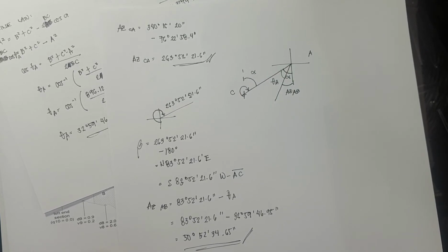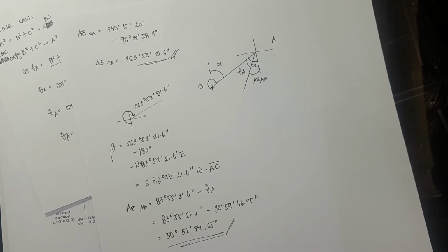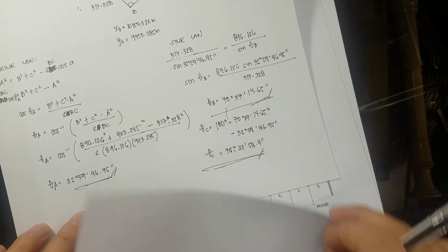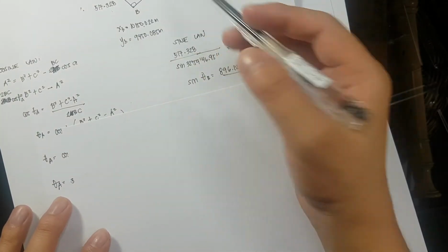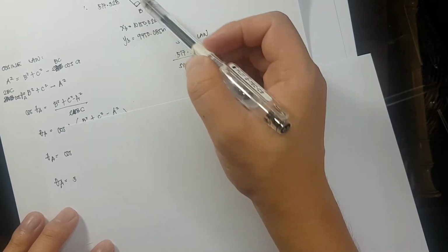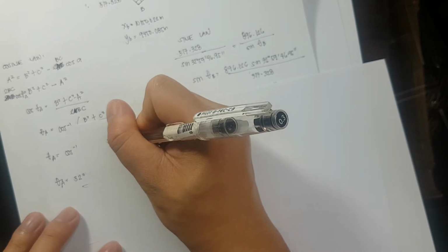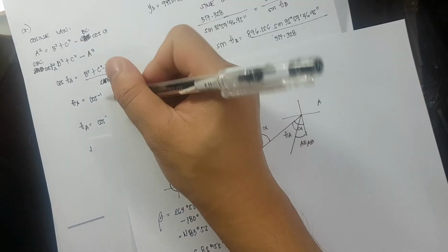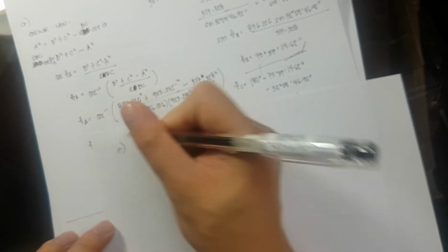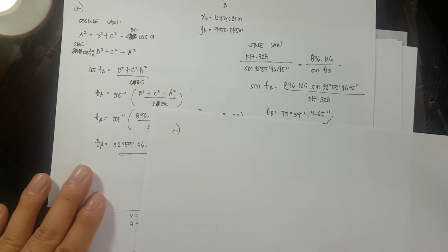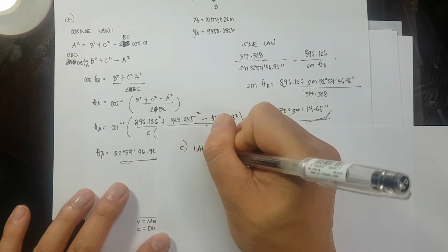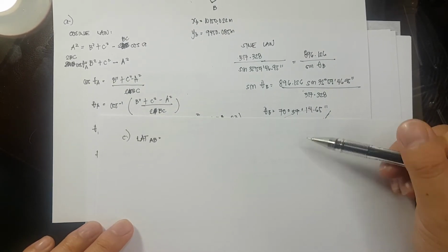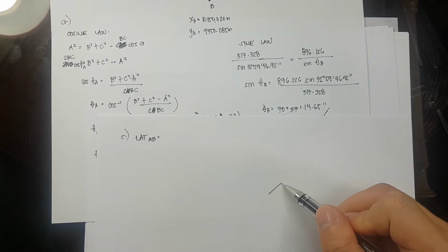Next, we determine the coordinates of points A and C. To solve for the coordinates, we need first to determine the latitude and the departure of CB and AB. Okay? So, this is A here, this is B, and lastly, we have letter C. Now, we need to determine the latitude and departure. So, latitude AB is equivalent to, take note that latitude is the vertical. Okay? So, i-redrawing natin, that is AB. So, AB looks like this.